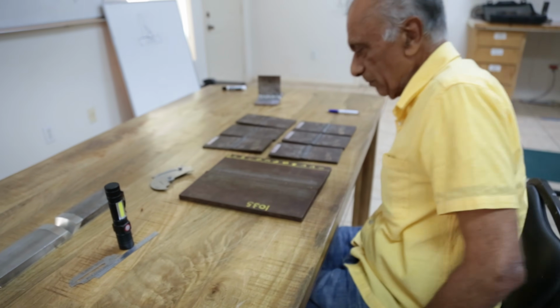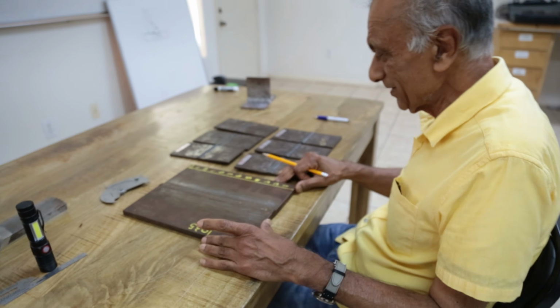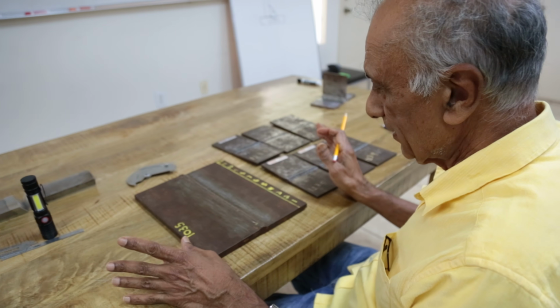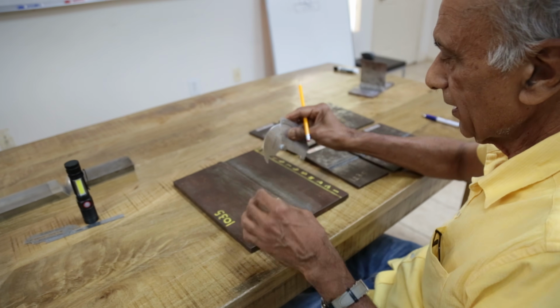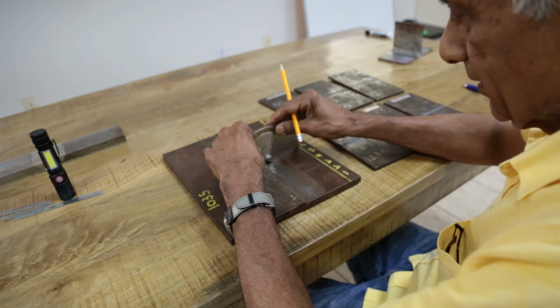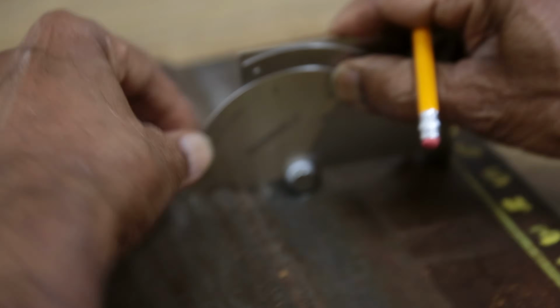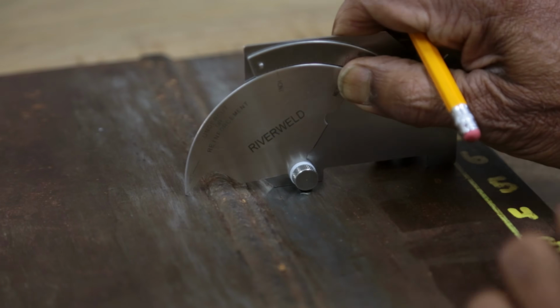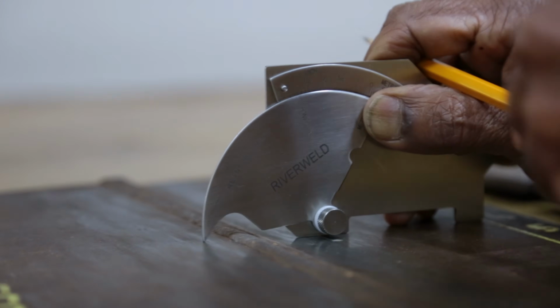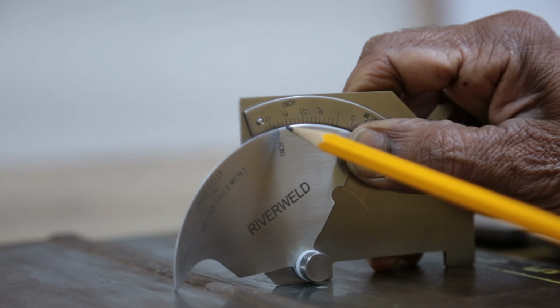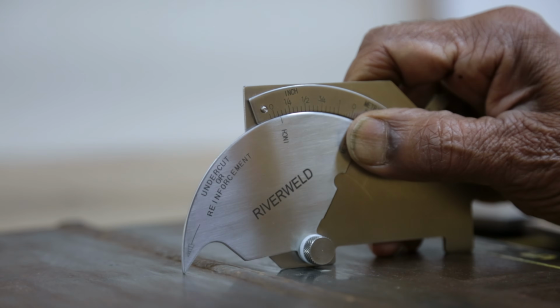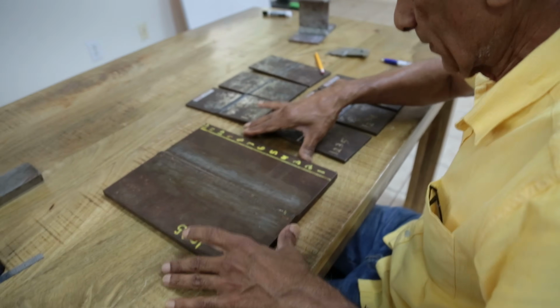And once the welding is completed, then we come over here to these parts. The final weld is complete, and this part has misalignment. Again, you put the gauge here, and then you can check the misalignment by putting the gauge on one side and this pointer on the other side. And from right here, you will see how much misalignment is there and whether it is acceptable or not acceptable. So that's misalignment, and here are some more examples.